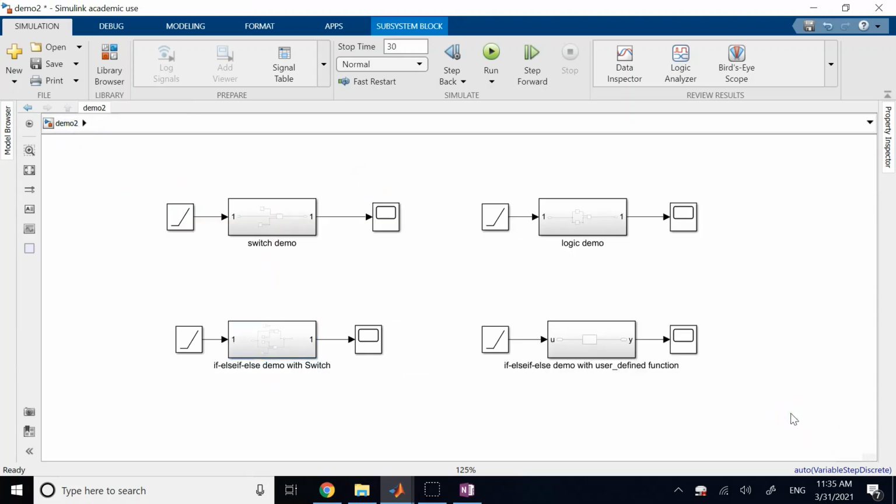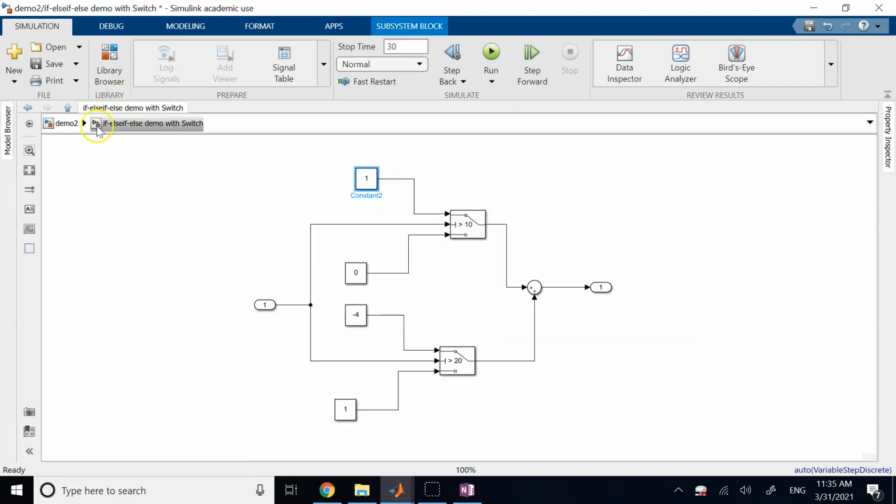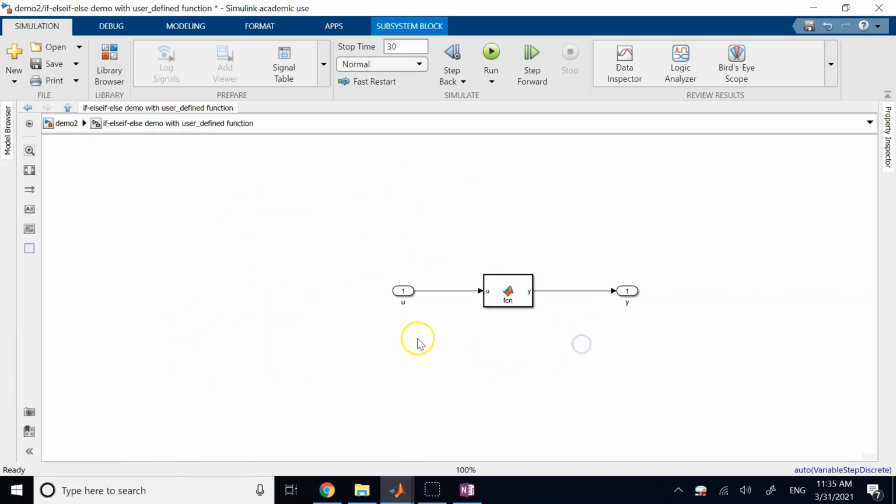Now you might say, is there any other way that I can do it? And the answer is yes, sure. This time, instead of all this wiring and stuff, I put all of that in the code, because Simulink is really good for connecting blocks and everything, but sometimes maybe if I want to create something like a for loop, a while loop, if else, and other of those what we call logic flow controls, it's better that we directly code them instead of connecting blocks to make them happen. So what I will do here, I'm going to bring a MATLAB user-defined function, okay?